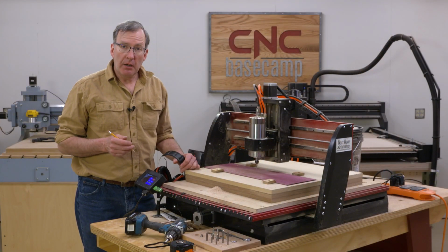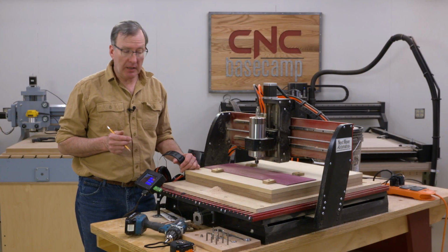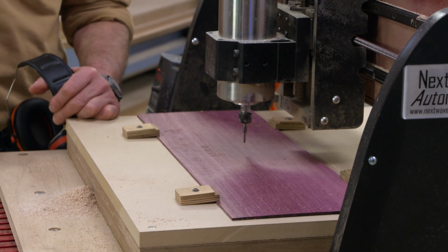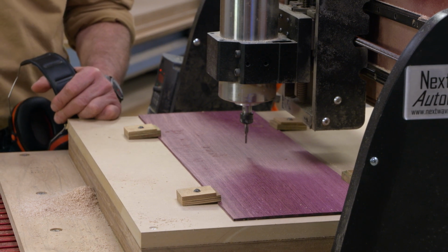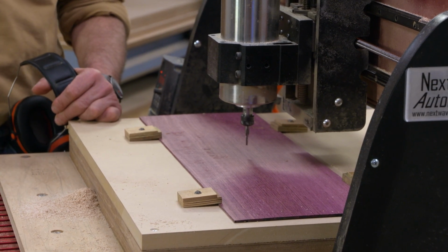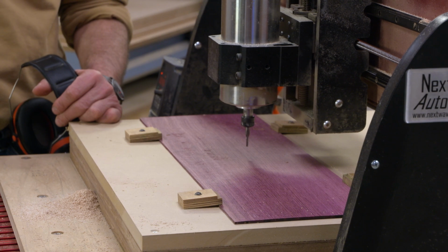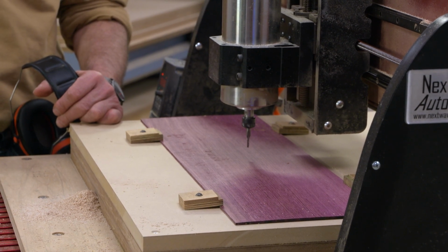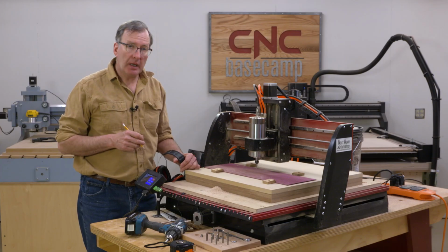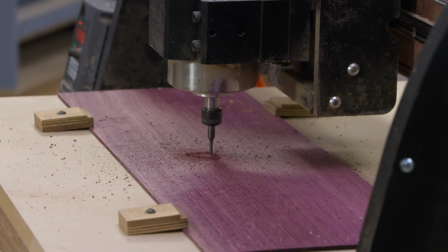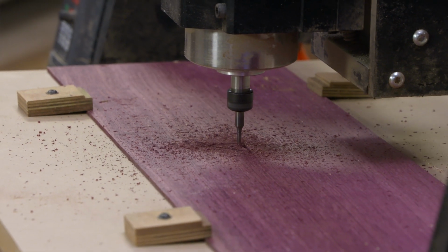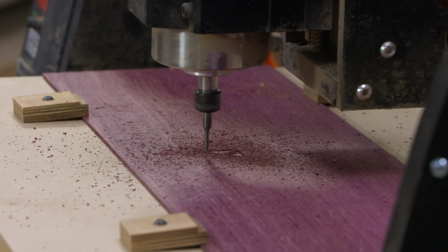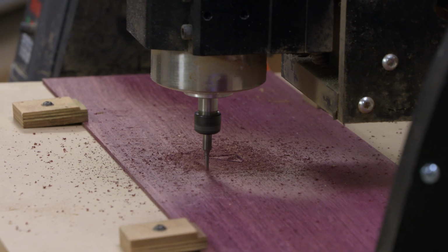Well, now it's time to cut all the little parts to fit into that panel. So I've got a piece of purple heart here, which I think ought to be really pretty. I'm very excited about it. Using an 1/8 inch straight bit, and that's going to give good clean sides to all my parts. They'll fit nicely. Now I will tell you one thing I have done is I went ahead and shrank my parts down to about 99% of original size, and it's just going to make them fit a little bit easier. Makes it a little easier on myself.